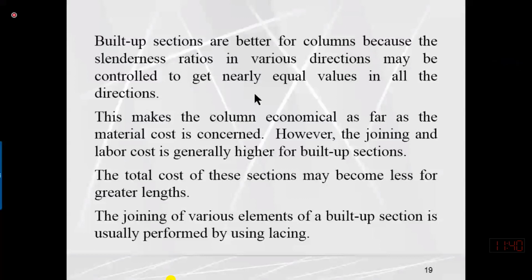So what advantage are we getting? The total cost of this section may become lesser for larger lengths. The joining of various elements of a built-up section is usually performed by using lacing.